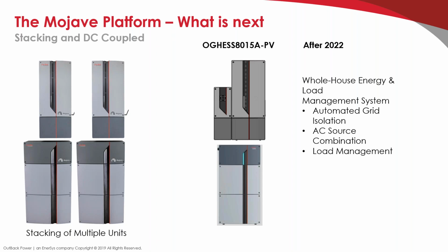But what that means practically is, starting in the back half of this year in California and Hawaii, you're going to run into trouble from utilities and AHJs allowing you to interconnect the Radian because it can't do those extra special things you're supposed to be able to do with this new standard. That will probably be nationwide by the end of, say, 2023 or 2024. So the Radian will work totally fine off-grid. It'll still do all the things it does today. It's just you're not going to be able to get your interconnection agreement in some states, as they adopt this new standard, and that's why we'll be transitioning to this platform.